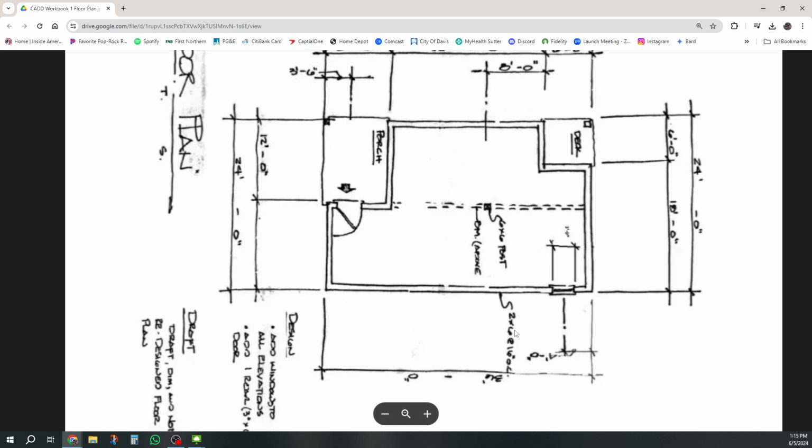The reason we want this 2 by 6 is that it tells us that the wall framing, the inside edge of the structure, the core, is 5.5 inches. A 2 by 6 is 5.5 inches. A 6 by 6 post is 5.5 by 5.5. And you'll learn more about those dimensions when you take Design 300. So that's kind of what we need to know.